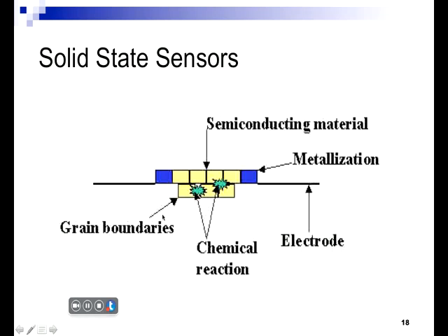The way that they work is that the chemical will come into contact with the sensor, and the sensor is going to be specific for detecting that particular type of material, and it'll cause a chemical reaction. When a chemical reaction occurs, you're going to have a change in current. And when that change in current occurs, you can trip it to an alarm system. So these are very good for measuring low concentrations of certain types of contaminants, particularly in remote areas where you may have a leak occurring.